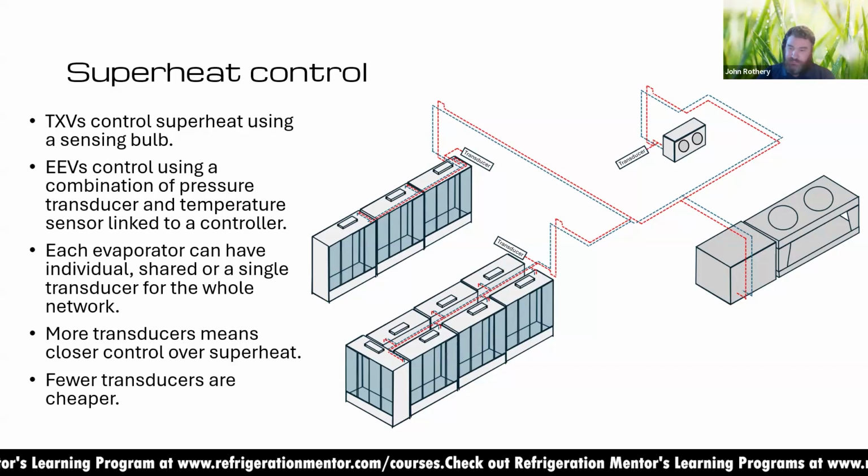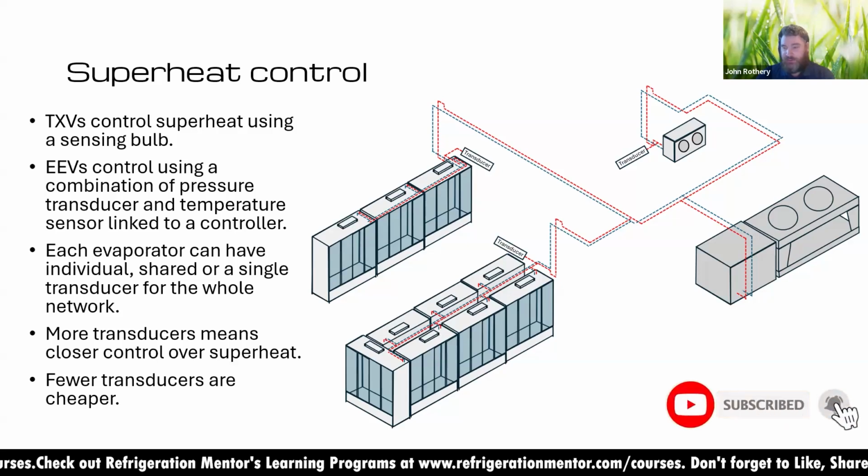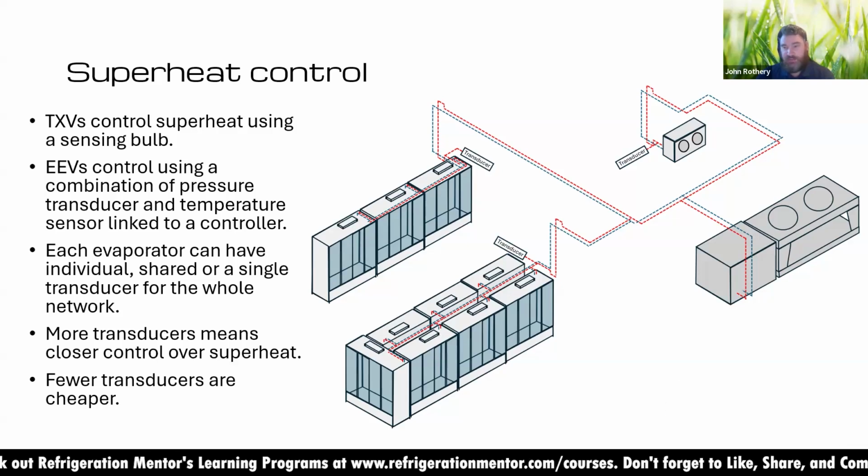Yeah, so obviously with the new systems, I can dial into a store remotely. On the contract that I was working on, I could actually look at the fault, diagnose the fault potentially before the engineer even arrived. So it's great for a steer. If I'm seeing flood back or low superheat on something, I can shut it down remotely as well, protecting the compressors, because obviously you've got the big cost if you start getting flood back through a cabinet, for the sake of a transducer, and you're risking compressors failing, etc. It's a no-brainer, really. But yeah, it's great.